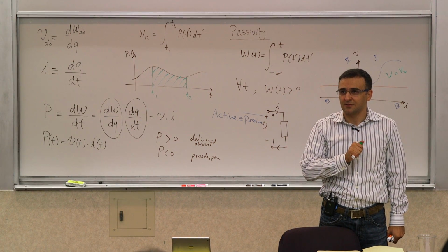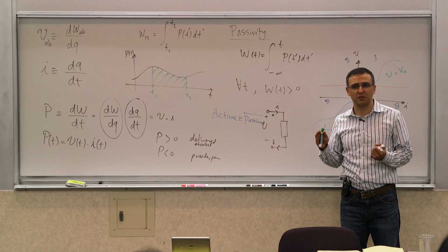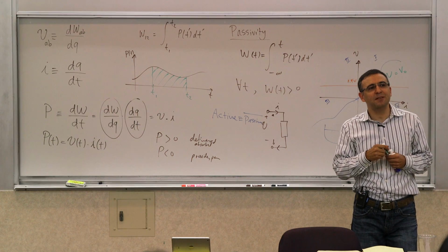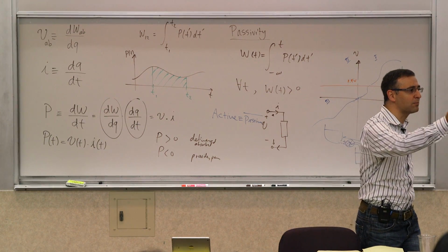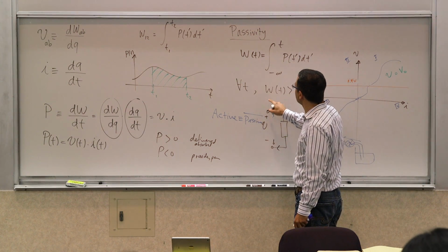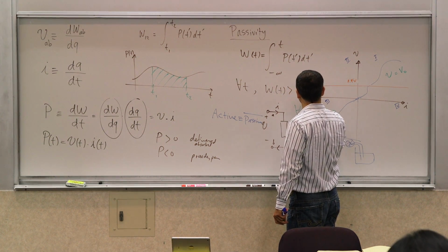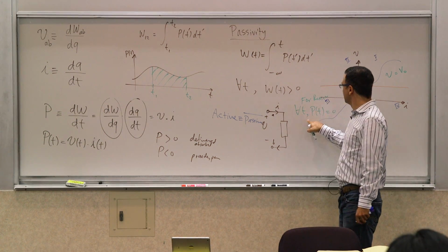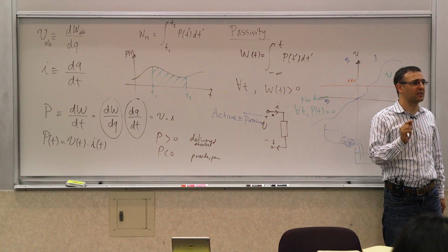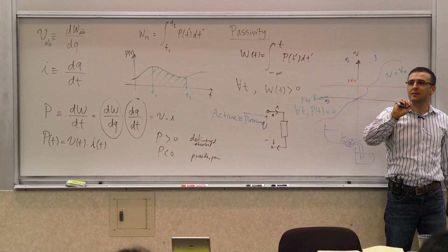But going back to the capacitors, right? So capacitors technically are what? What conclusion did we arrive at? Passive or active? Passive, right? So they're passive. However, they're a special kind of passive. They are passive that at some point can provide energy to you. A resistor cannot. For a resistor, not only is this true, but this is also true, because of this IV characteristic. In a resistor, even the instantaneous power cannot be negative. There's not one instance where it can actually provide power.